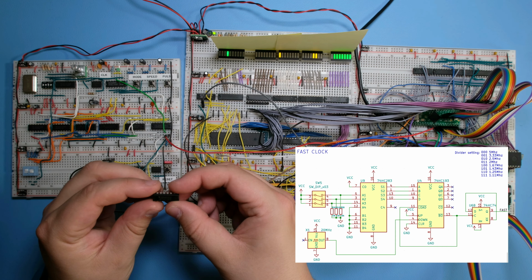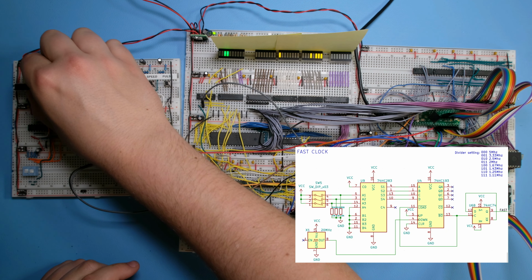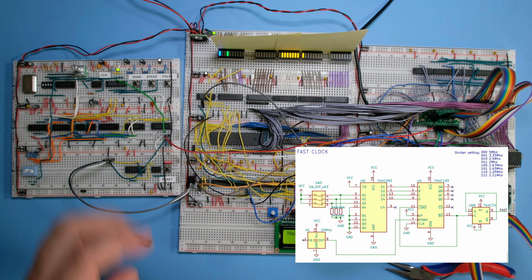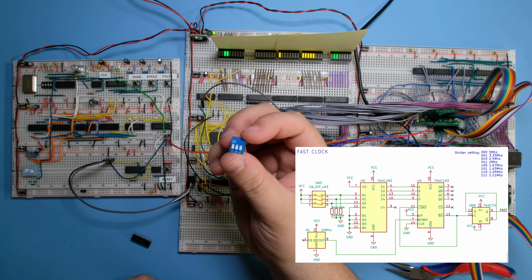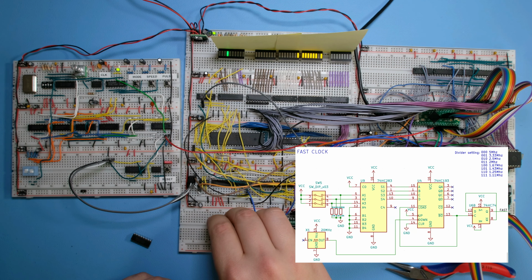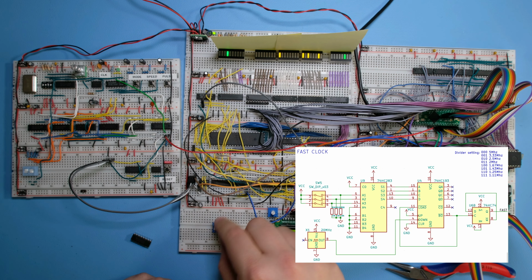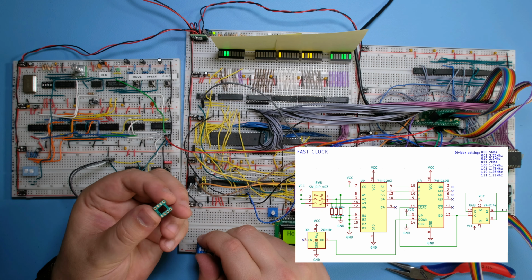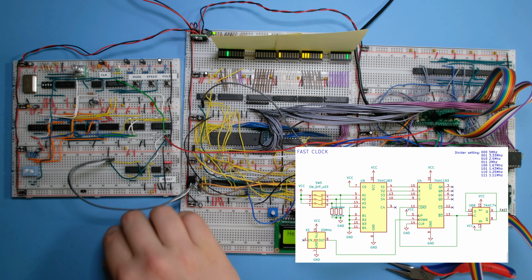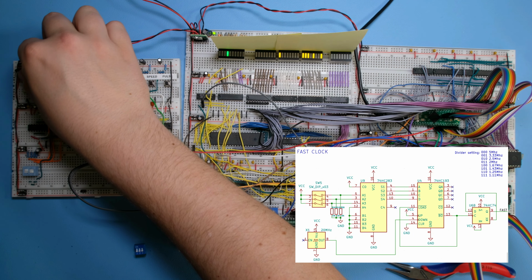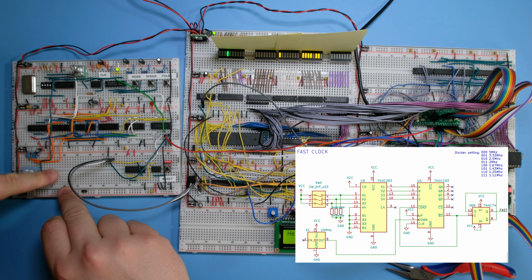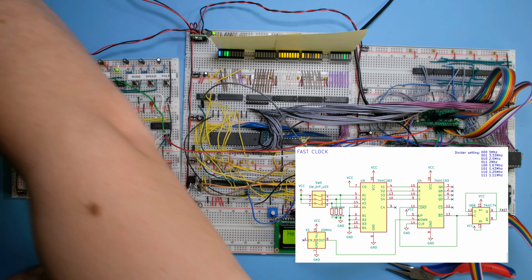And I have here a 74HC283, which I'm going to put here in order to compute the dip switch. And I have a 3-bit dip switch here. Unfortunately, it doesn't really want to stay in the breadboard properly, so I'm just going to use a socket that I know is going to stay in place. So I'm going to put the 4-bit adder over here where the oscillator is, and I'm going to move the oscillator down here. Let's get started.